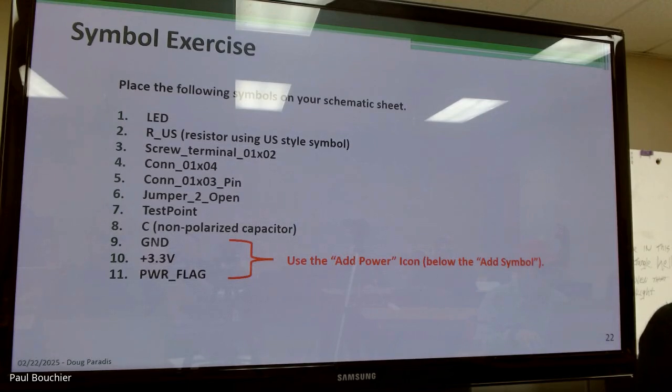You can populate them with the standard DuPont type headers or pin headers, or you can put the XH, and they have the advantage of being polarized and clickable, which makes your connections a lot better. Okay? And there's no more work.